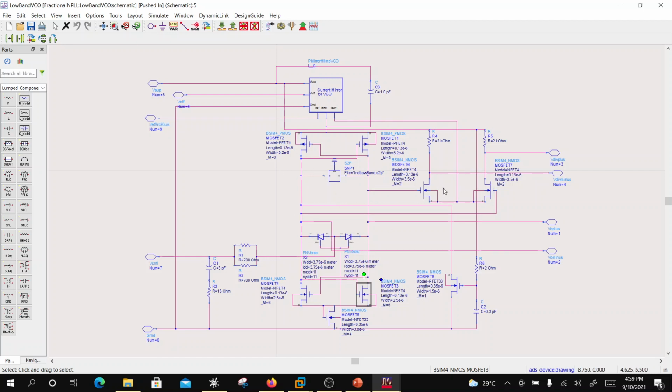And then there is an output buffer. We may not have a buffer, but that's okay. And then these varactors are the 2 capacitors, right, which are controlled by this voltage we control. So there is a net voltage across these diodes, okay, which decides the capacitance, and that establishes the frequency of this VCO, the output frequency. So by controlling this control voltage, I can control the output frequency.